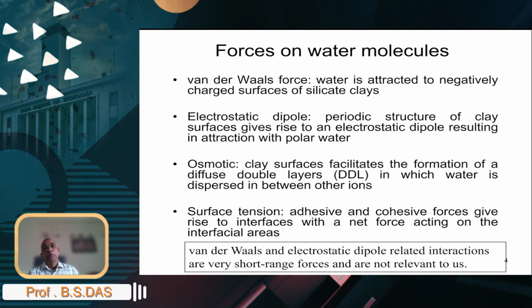For the short range ones, the two forces, van der Waals force and electrostatic dipole effects, basically arise because the soil, as you remember, has one component of the solid phase that is clays and soil organic matter. Both tend to hold unbalanced, excess negative charge, and so they have the capacity to attract the positive head of the pole of the water molecule.